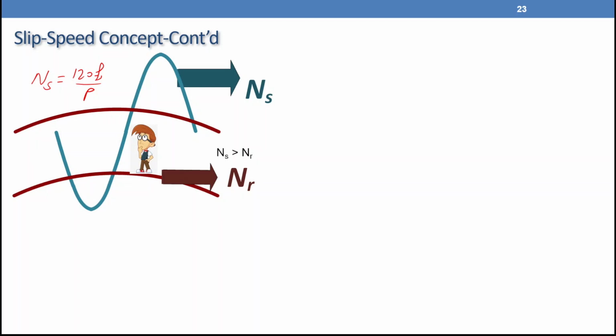He said that above me, I see a rotating field running at synchronous speed. And below me, there is a rotor running at Nr speed in RPM. So what about you? He said that I'm slipping by the difference between Ns and Nr, where slip speed equals Ns minus Nr. So we can say that slip speed equals SNs.